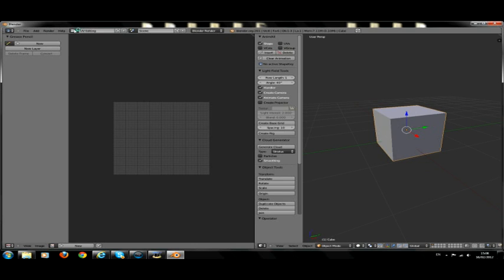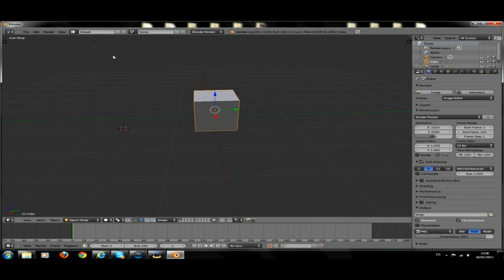And to add that layout to the full version of Blender, you press Control U, or you can go File and Save as default, and it'll be saved into the actual main Blender file. So if you have a different screen layout you want to use for a different type of editing, you can put it up here.